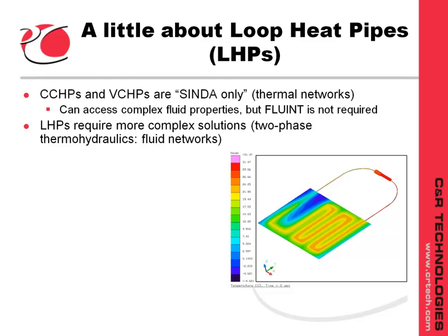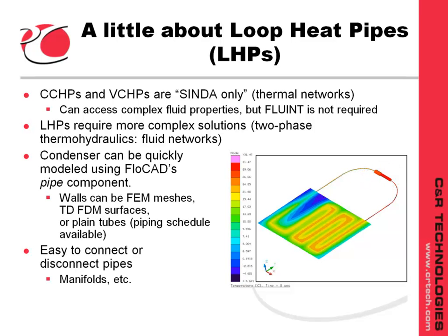But it also means that there are more choices that must be made, especially with regard to specialized modeling requirements of the capillary evaporator pump and the compensation chamber, two devices which do not exist in a pumped two-phase system. Many complex LHP systems have been successfully analyzed and references are available on our website. But you should be forewarned that successful LHP modeling requires more knowledge of what's going on inside the loop than is true for traditional heat pipes.